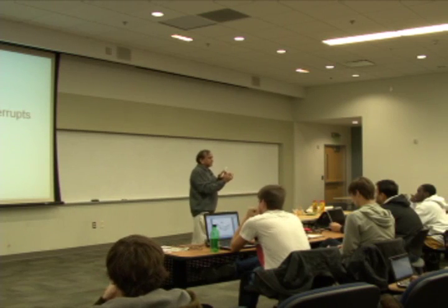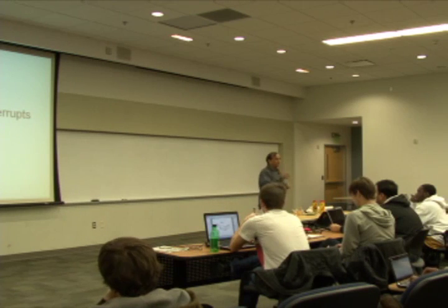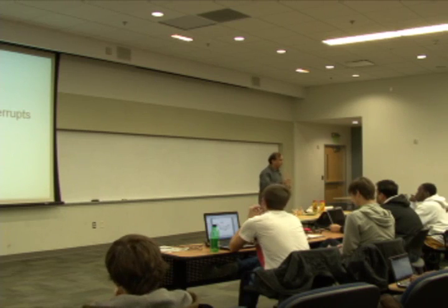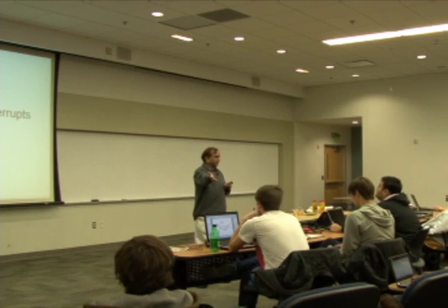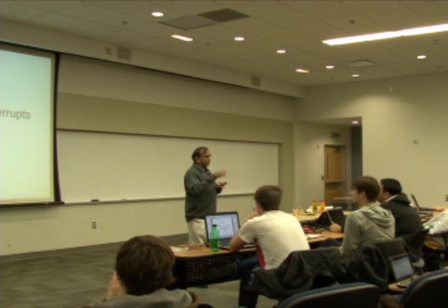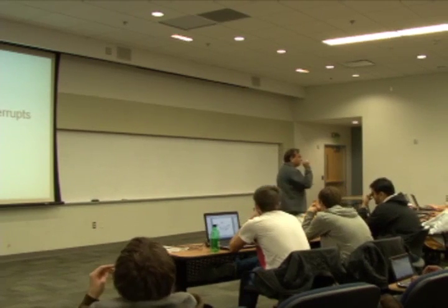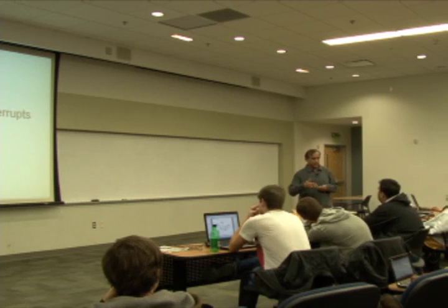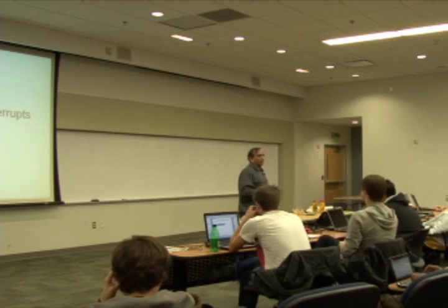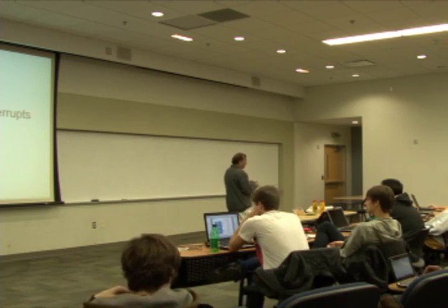So there are three types of interrupts, three types of, I'll call it program discontinuity, going away from what you're doing normally. One type of program discontinuity is the external interrupt that Taylor pointed out. The second type is what Michael and Shane pointed out, the program discontinuity that occurs because of your error in writing the program. You have an overflow, underflow, or a divide by zero. All these kinds of things result in program discontinuity.